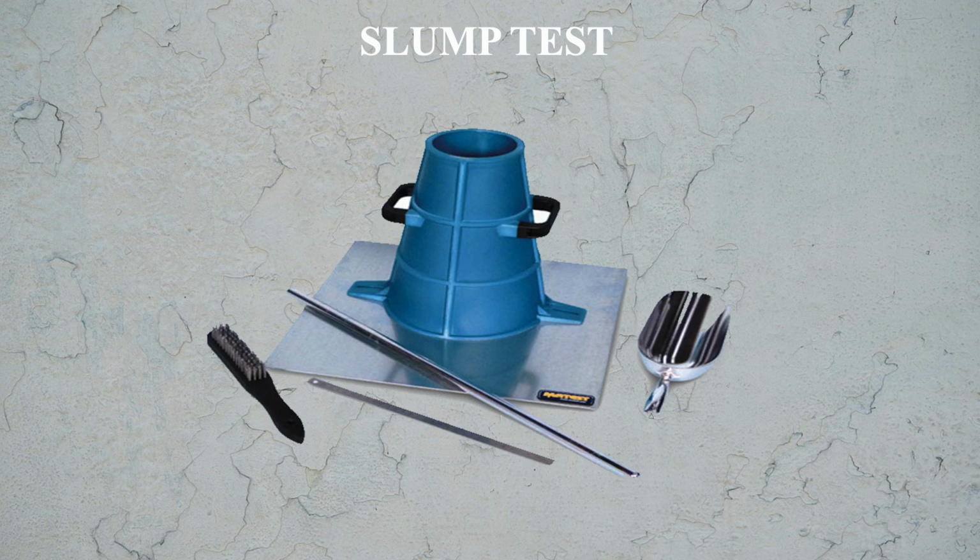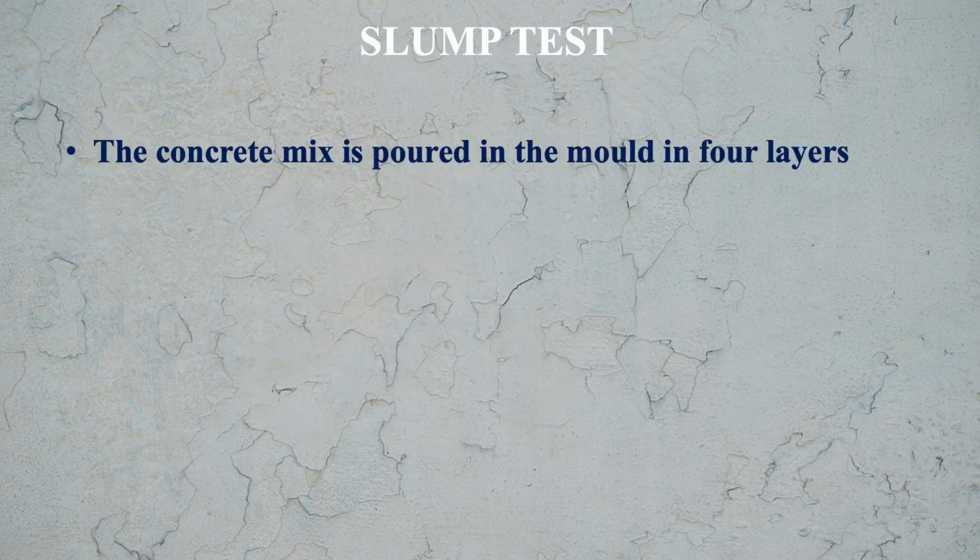Here you see the picture of the actual mold and other things. Here you see the mold and the tamping rod, the measuring scale, brush, all these things that you see in this picture. So what we do in this test, the concrete mix is poured in the mold in 4 layers, each layer 1/4 of the total height of the mold.